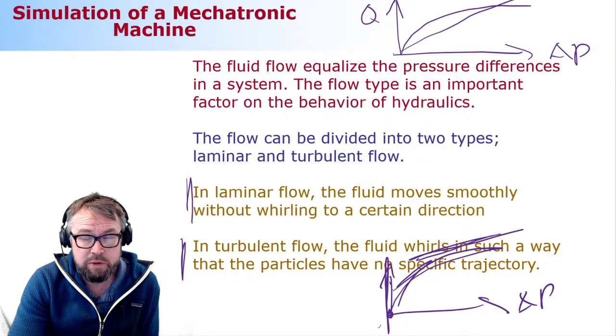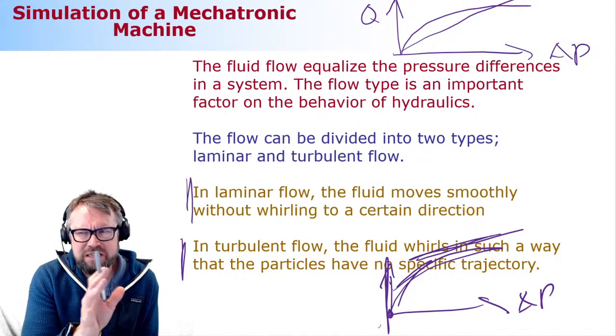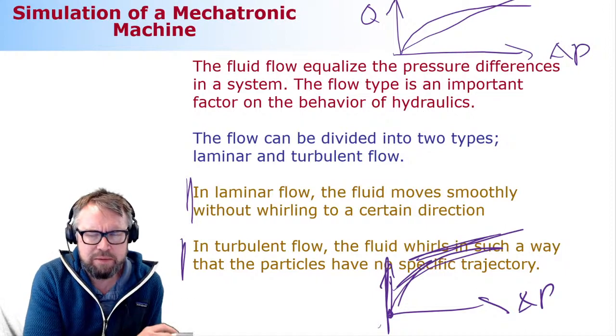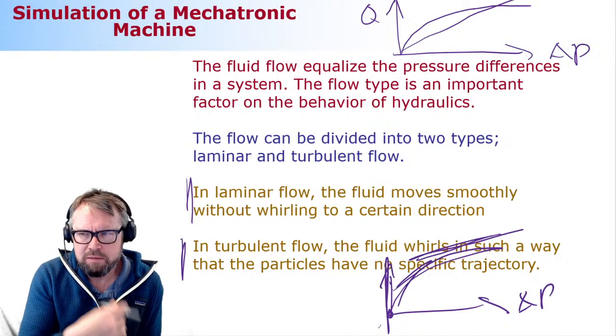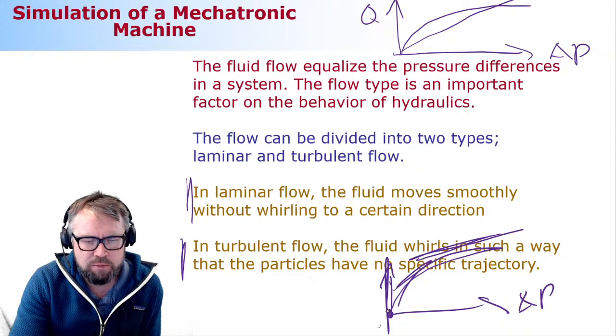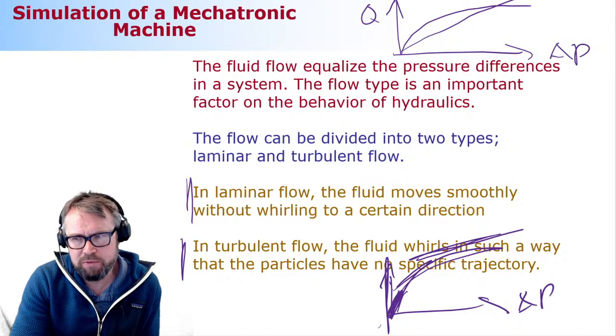So numerically it is hard to capture that at zero pressure difference the flow rate is zero, if modeled using this turbulent framework. So what you can do is assume that at a very small pressure difference there's a linear regime, which helps you perform this numerically more efficiently.